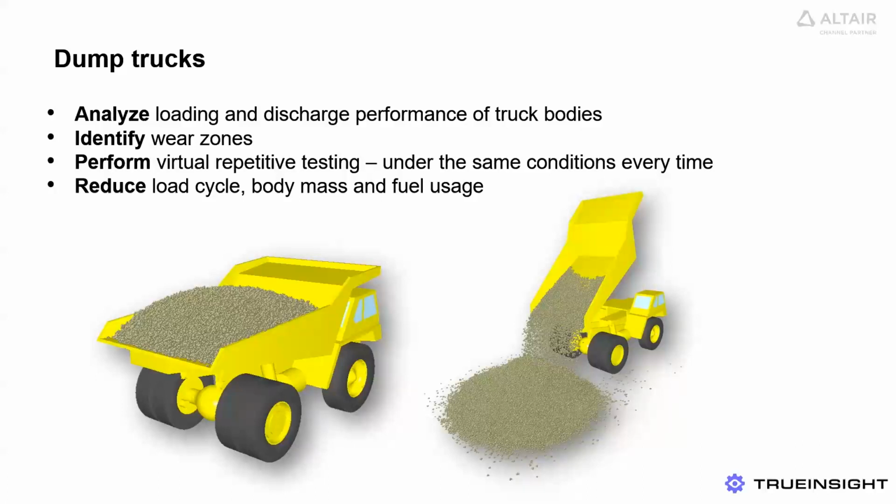Our first example is a truck body. Truck bodies typically need to load and unload material quickly and without spillage or hang up to be efficient and reduce fuel consumption. EDEM can be used to analyze the loading and discharge of truck bodies, identify areas that are subject to higher wear or areas that material will hang up. You'll see an example of this in the next slide.